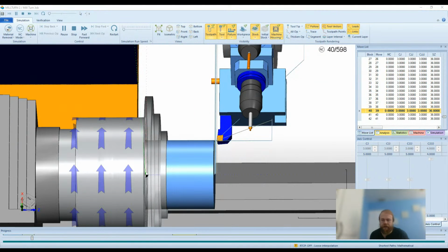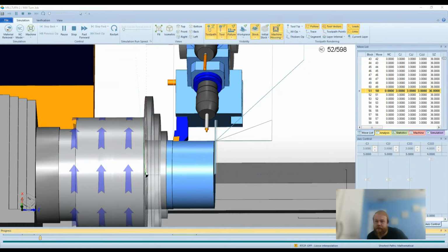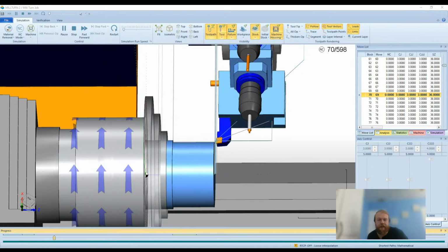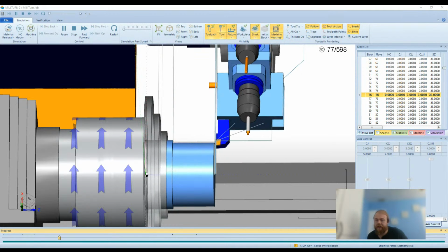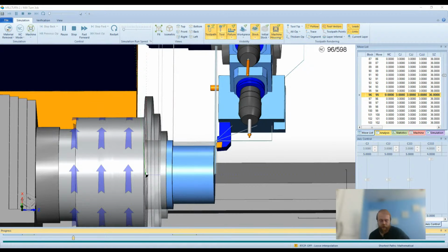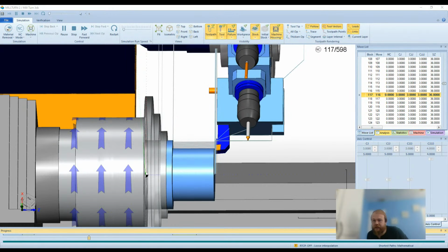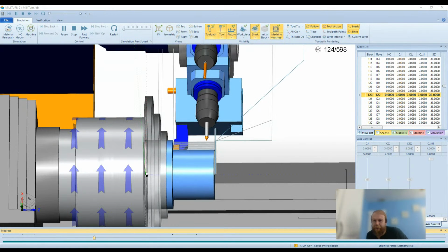Let me see if you guys have any questions with the mill turn there. And you can see that red it's showing when it hits the spindle there of the main spindle with the turning tool. It'll show that there is a collision there. So we'll either want to have the stock sticking out a little bit further, maybe an extra amount of stock there to be cut off, or something like that.